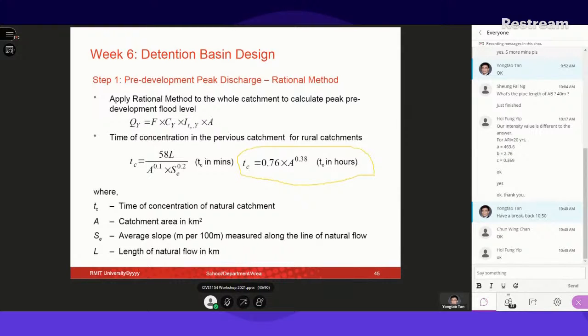It depends on many factors such as land surface, slope, degree of saturation, the rainfall intensity, and the temporary storage of the catchment. It is also affected by the water table, soil compaction, vegetation, depression storage, and many other factors.